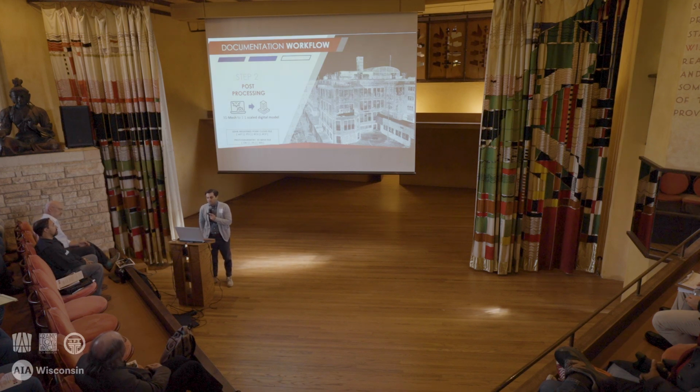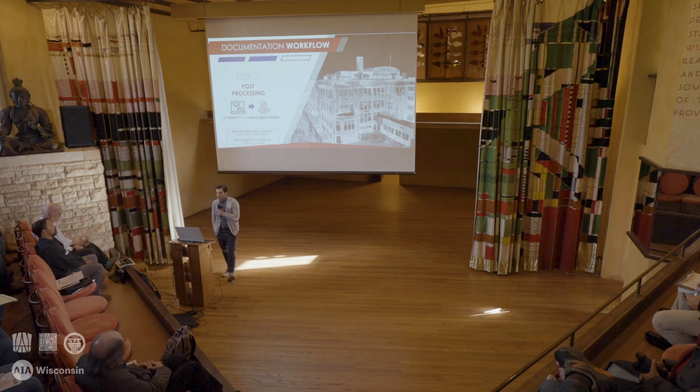But one thing I will say is that for archival purposes, in the world that we talk about, historic preservation, one key aspect of post-processing is getting your files to a point where they'll live in perpetuity and they can be used 6, 7, 10 years down the line. So the different scanning platforms do a good job of keeping all their files proprietary to their software. So they make it very difficult to process FARO scans in Leica software, Leica scans in FARO software, and so on. So jumping to that post-processing for archival purposes is usually a pretty good idea.